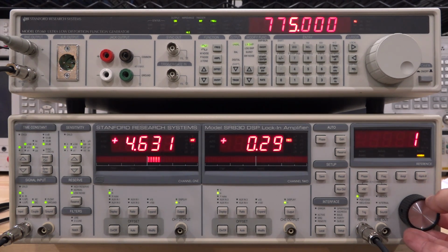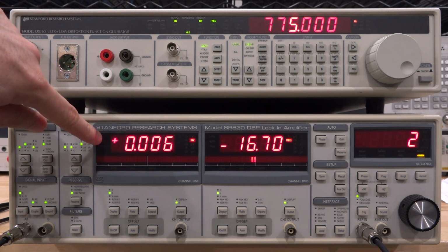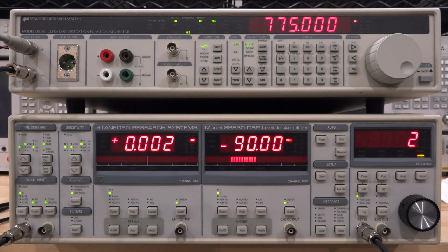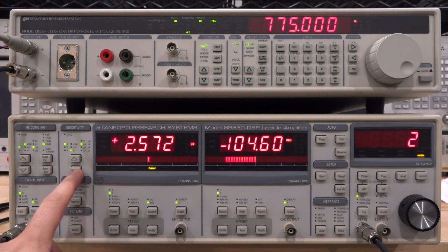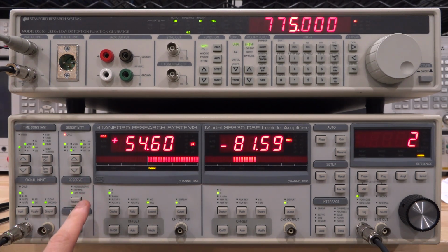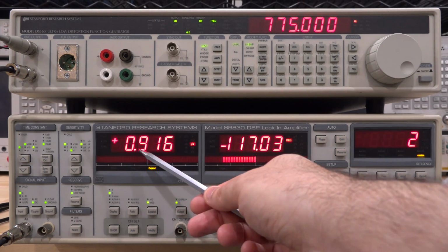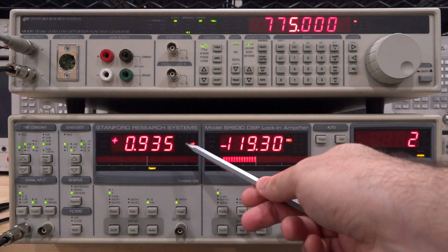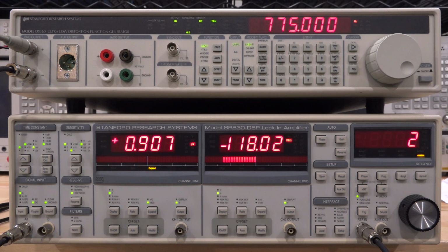There you go. As soon as we go to the second harmonic, we're going to see that this power, of course, almost immediately disappears because the power of the second harmonic is so much smaller. So we need to apply the expansion here and go down in range as long as it's not being overloaded. So we're in some desirable state there. Let's see where it settles to. There you go. So it is measuring about 0.8, 0.87, maybe even 0.9 microvolt RMS is the power of the second harmonic.